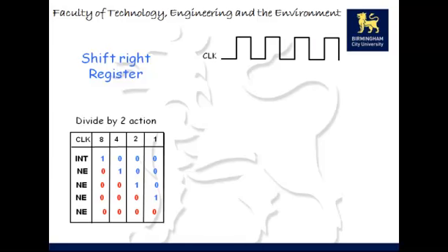We've got a clock pulse at the top, and this time there's an input of 0. Previously, for the generalized shift register, I put it as an X because it could be 1 or 0, but this time I'm going to load zeros into the shift register.